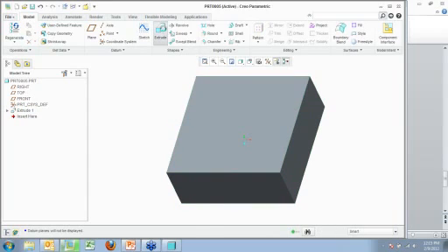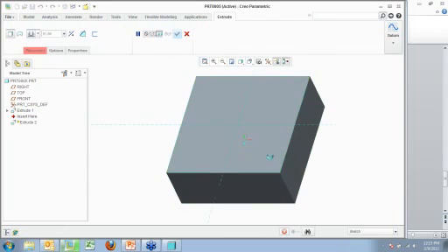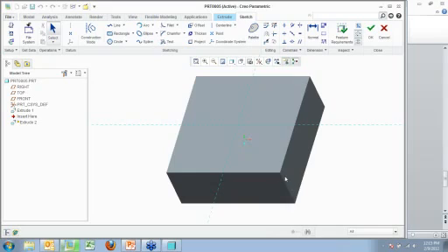I'm going to go in and make another extrusion right on top. Select this here. So I want it to snap to this corner here. I don't have to select the references. I can just go in, grab my rectangle. This time I'll do a standard corner rectangle. Well, I don't have any references to snap to, so I hold down the Alt key, and it pauses my sketch. You can see the point still hovering there in space. Select this, let go of the Alt key. Now that's a reference.